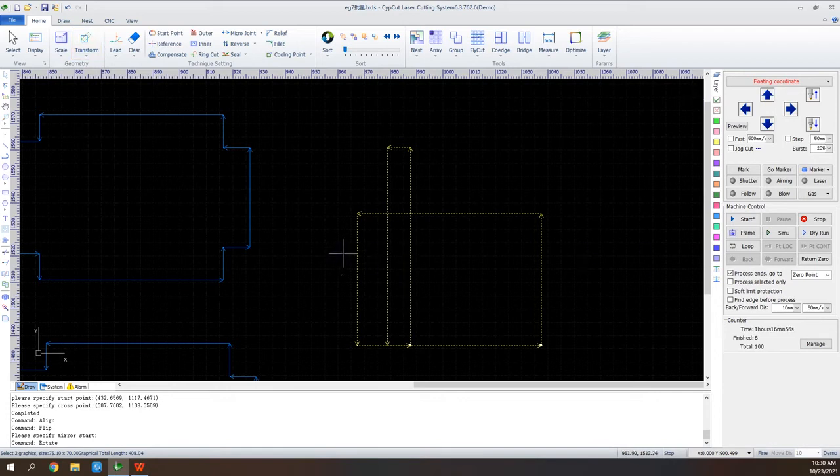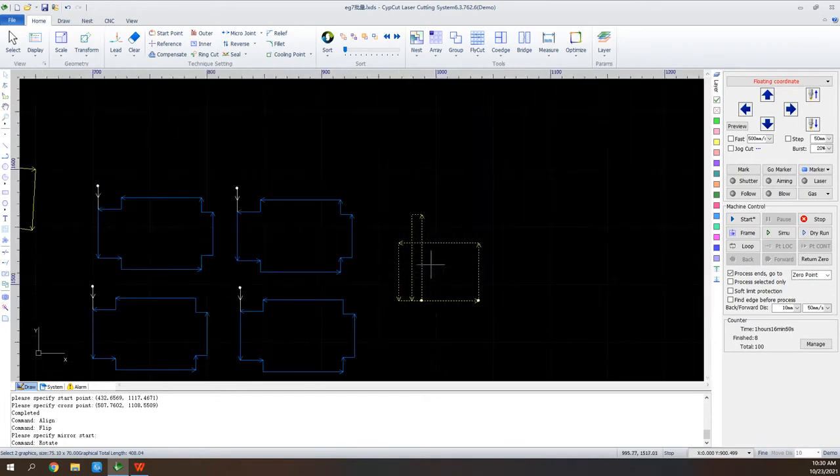Flip vertical, or we can rotate it. And when we laser cut parts, we make the cutting path start from several millimeters away from the part. This way it could get cut much better. The distance is what we call the lead.